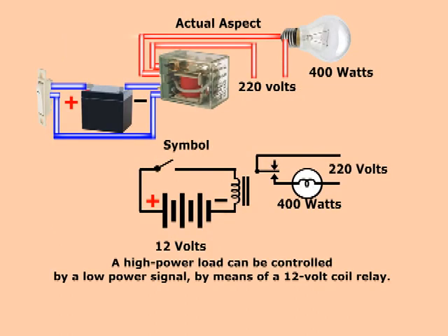For our next schematic, we are going to use a battery, a manual switch, a relay, and a high-intensity bulb, say, a 400-watt incandescent bulb, as in our example. By applying a very weak current, a fraction of an amp, from the 12-volt battery, to the relay coil, the relay contacts will pull together, thus turning on the incandescent bulb, which uses a much higher voltage, which can be 220 volts from the electricity company, with a heavier current, close to 2 amperes.